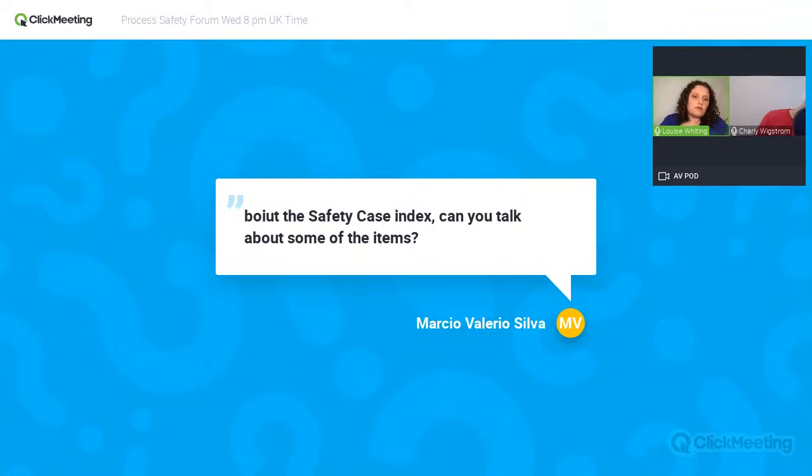The things I've seen work really well are having an executive summary, and having a process description, which references where you could find, for example, your PNIDs and all your operating procedures. And then having something which describes your hazard management process. So how did you go about assessing your hazards? And what were the main hazards that you identified? And then the next one is, how are you managing those risks?